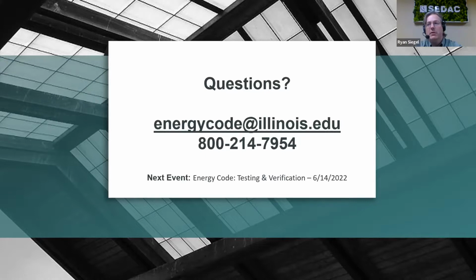So those projects that are already permitted or under construction prior to the effective date would still be under the old 2018 IECC with Illinois amendments, and then new permit applications after that approximate October 1st date would be following and enforced under the 2021 IECC with Illinois amendments. So that's where they generally do it based on the permit application date, not necessarily the permit issuance date. But check with your local municipality as far as how they do it.